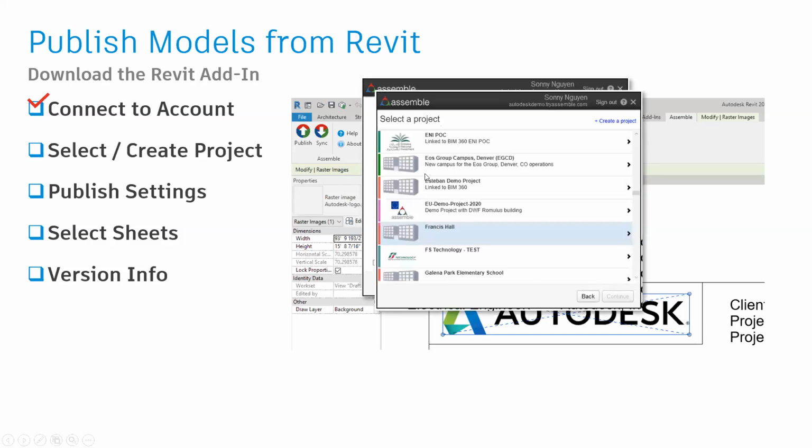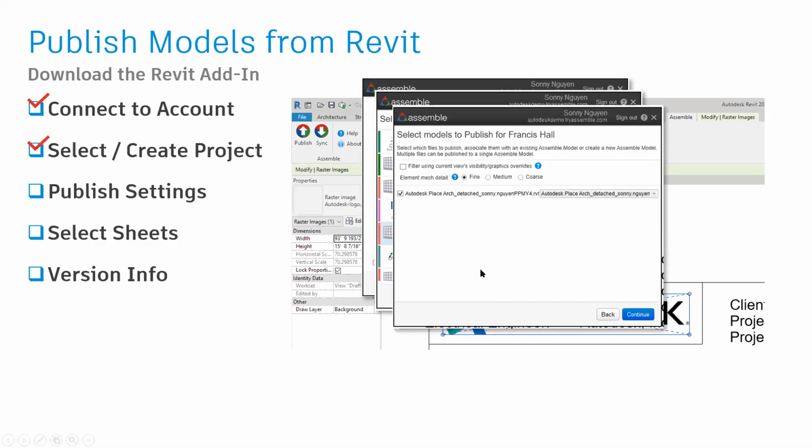Once you've done that, it's going to ask you to select a project to publish to. You can create a new project by selecting Create a Project, or you can select an existing project. In this example, we're going to do Francis Hall. Select Continue, and then we're going to have the ability to publish to existing models or new models within that particular project.